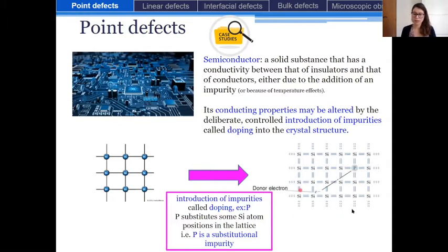And so very basically and very rapidly, and later we will be able to explain it, by making the substitution of one silicon atom by one phosphorus atom in the lattice position, this changes totally the electrical properties of the silicon, and it turns into a semiconductor, okay, by the introduction of this phosphorus.